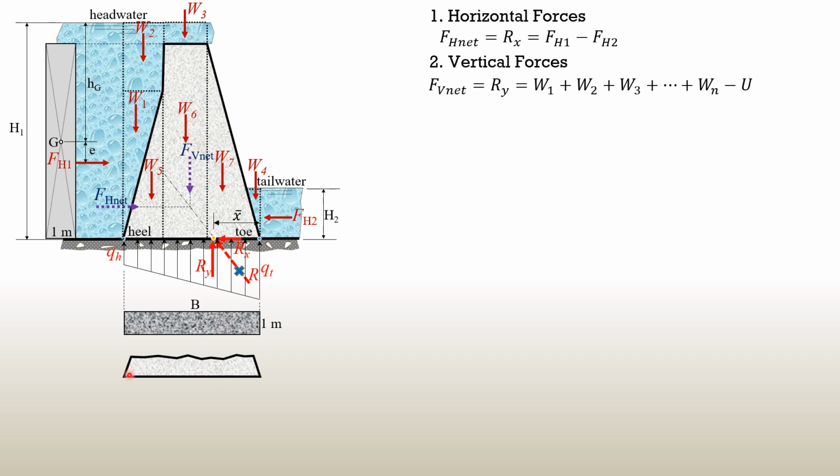Then this is the base of the dam sectioned, and if there is uplift, it is normally higher at the heel. It decreases from the heel to the toe with a certain coefficient or percentage denoted in geotechnical engineering with K. So K1 gamma of water H1, then this is K2 gamma of water H sub 2. So these Ks here are specified in the problem in hydraulics. So this is the uplift force, which is equal to the volume of this uplift pressure diagram.